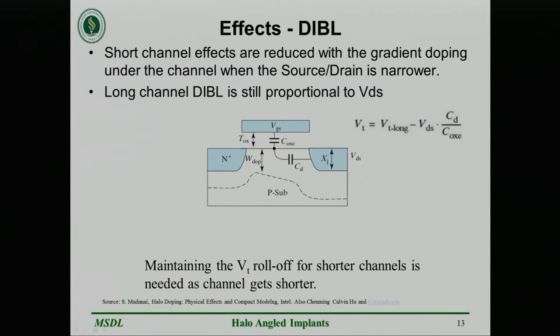You can think of this as the change in threshold voltage delta VT relative to the change in drain voltage. One way to look at DIBL is with the added CD capacitor in the diagram of the gate. CD has electrostatic coupling between the channel and the drain. As the channel length is reduced, the CD capacitance will increase. Graded junctions add more forward bias capacitance in series, bringing down the CD to further reduce these effects, but not for reducing junction capacitance in the opposite bias mode.